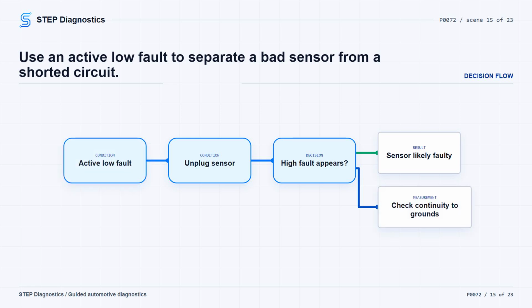If it does not, isolate the circuit by disconnecting the ECU connector and checking the temperature signal circuit for continuity to both chassis ground and the sensor ground circuit. If continuity is present to either one, repair the signal circuit for the short. If the signal circuit is not shorted, go back through the connector inspections before making a control module decision.